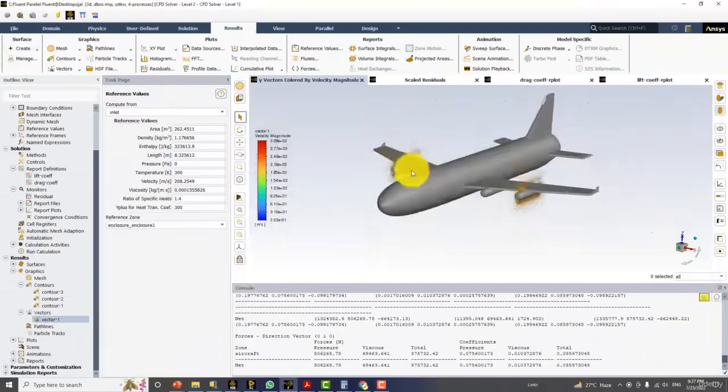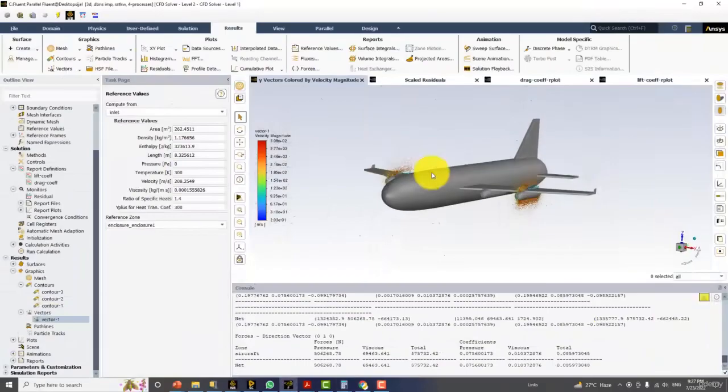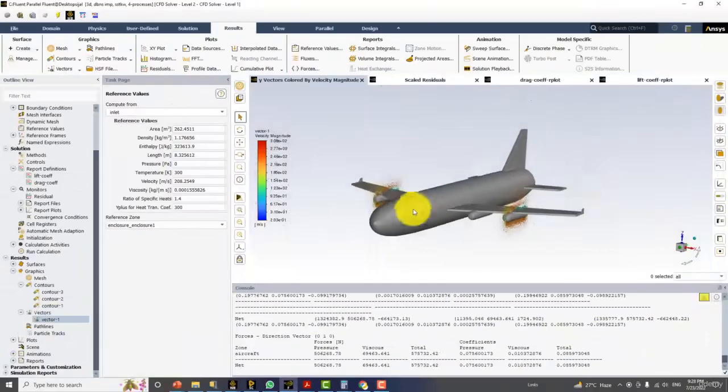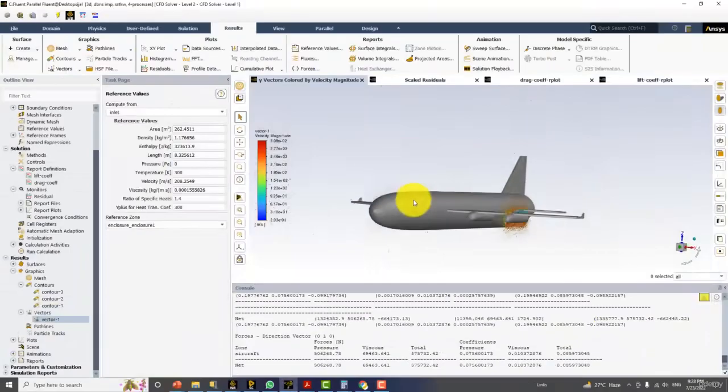Now, if you apply the same technique which I taught in this course, you can get accurate results even for the actual case of the Boeing 747-400 model. Okay, this is the whole thing: you can learn quick CFD on a very complicated model, making the geometry, domain, and the high quality mesh with the prism layers, with the refinement region in the wake, and also refined mesh on different parts of the aircraft, and running the simulation as a compressible flow with the inlet Mach number condition.